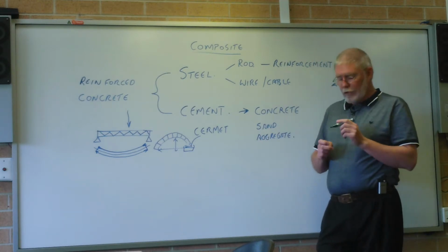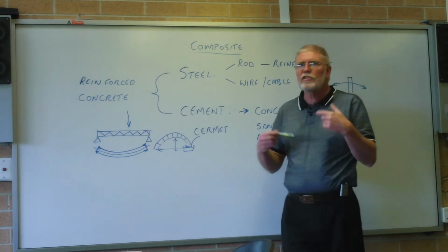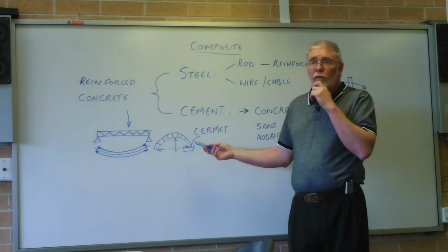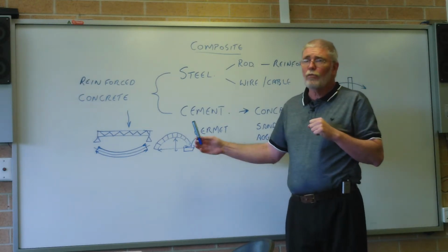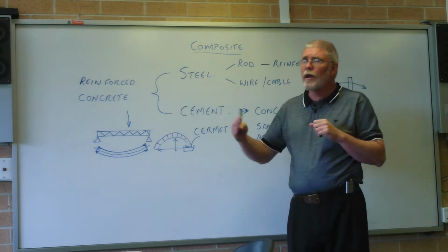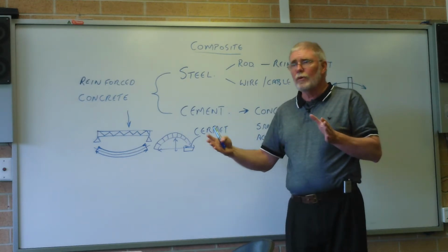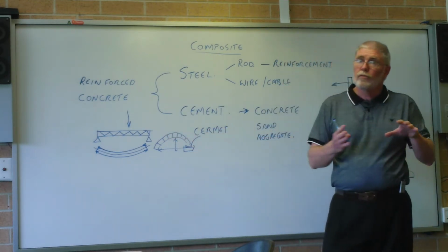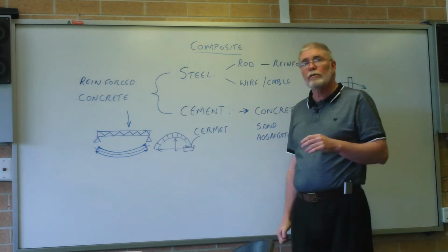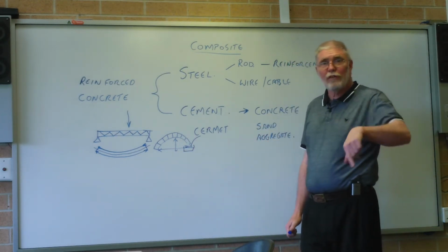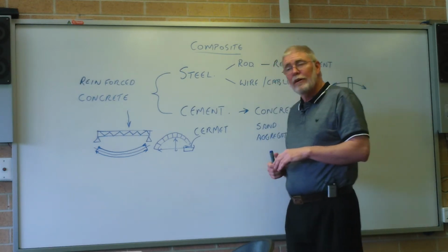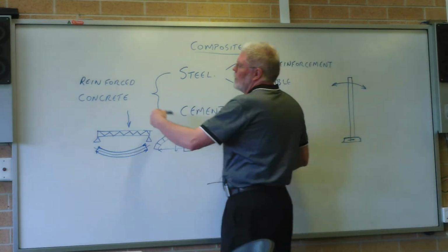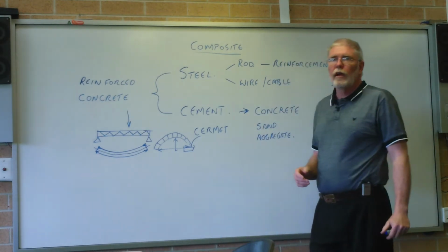A lot of places, we don't seem to have the issue here because we just don't think of it. But in a lot of northern European countries, the biggest problem to a bridge is ice. A lot of bridges in Russia and through Norway and Scandinavia, when the winter comes and the ice forms, and later when it starts to break up, you can have flows of ice coming down and ramming up against the bridges. It's fairly solid, it's not flexible, it's not going to flow around, it's going to back up and cause problems. So there's a few things about those types of structures that limit how far we can go, which is why we now tend to have steel as an option and concrete.